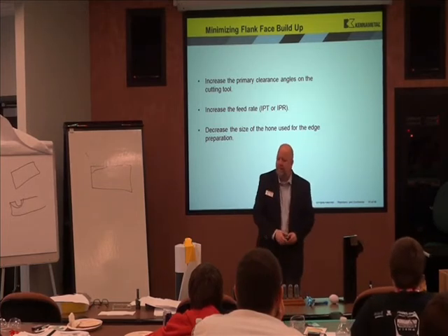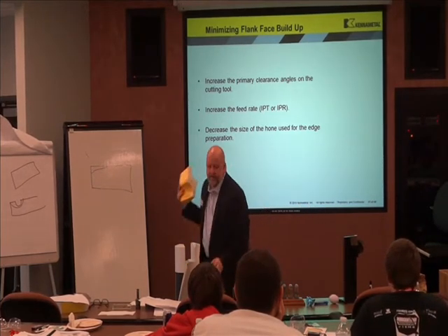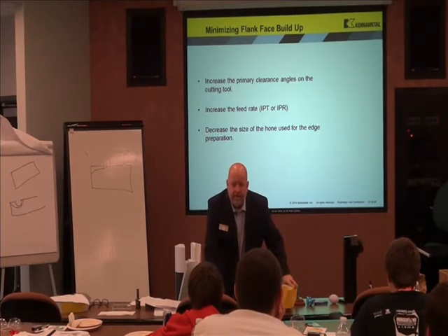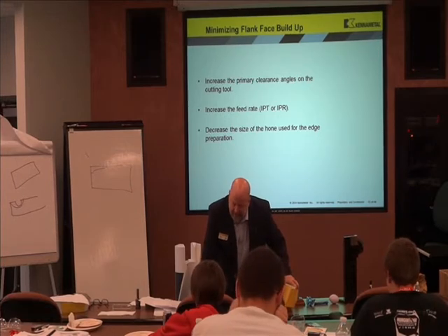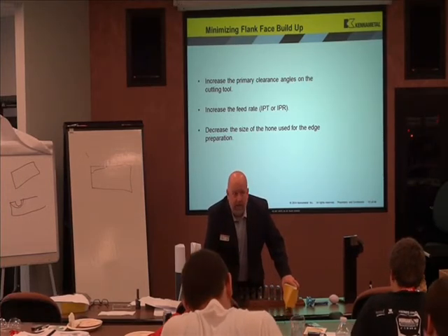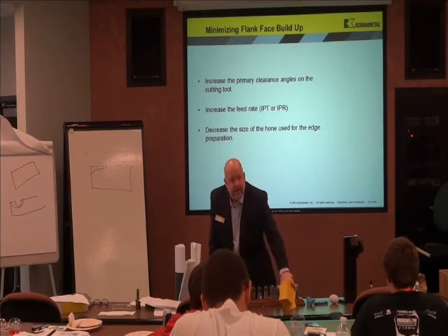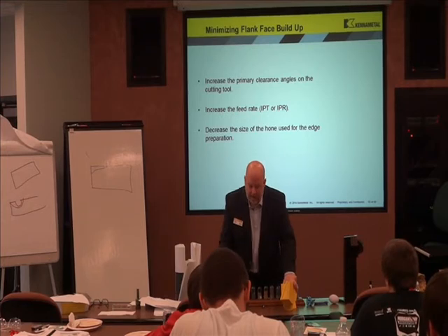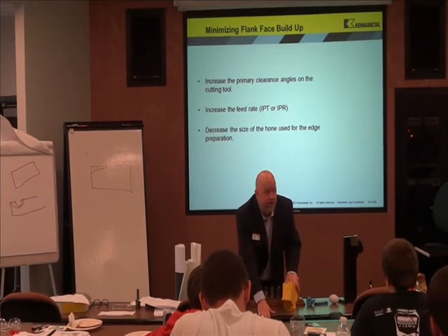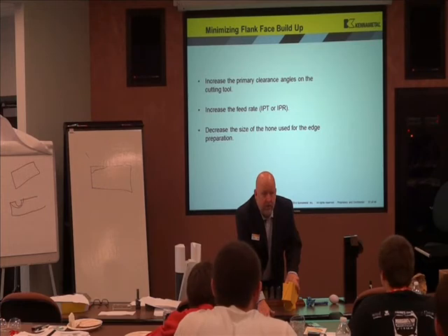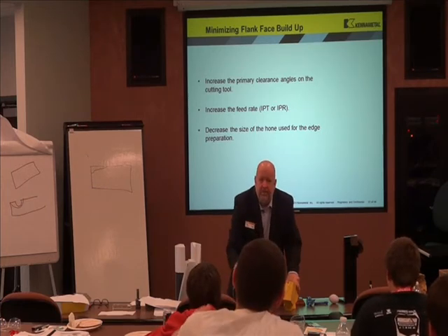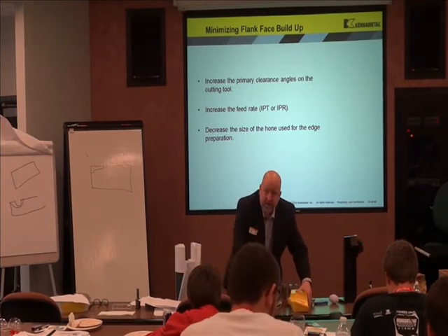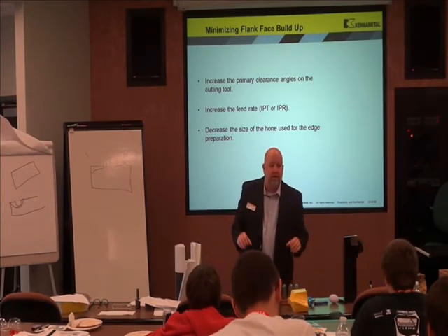Now, we didn't talk about this because that's actually in the middle of your book, but every cutting tool, if you look at your desk, look at this desk. If you look on this side, this edge of this desk is very rounded, right? If you look at this edge, it's not, right? That's edge prep. Why do you think we put this nice big edge prep here? So you wouldn't rub up, it's more comfortable, right? Okay? Here we don't care. We change the edge prep from this to more dead sharp depending on the material.